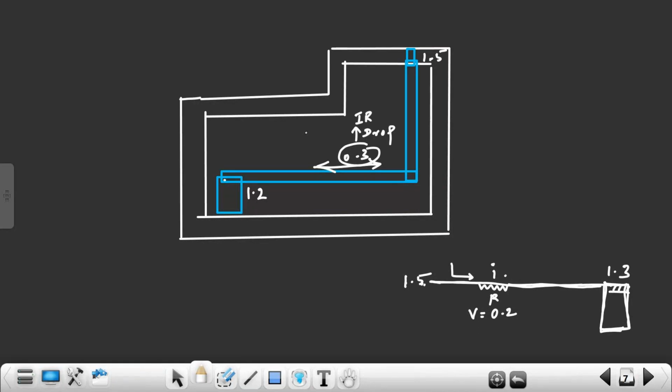So we have to do power planning in such a way that all cells are getting power, VDD and VSS, with negligible IR drop. So for that reason, we have to start with planning the power, how to distribute the power to all the cells without IR drop. That is the main role of power planning.